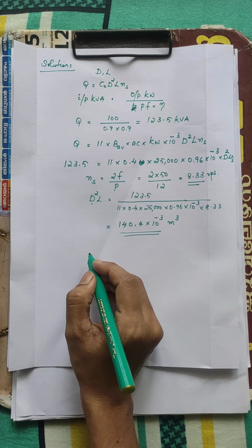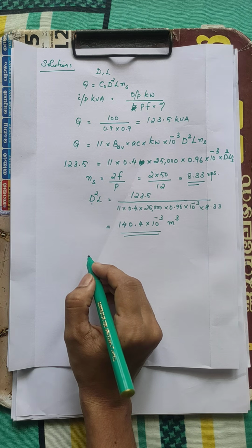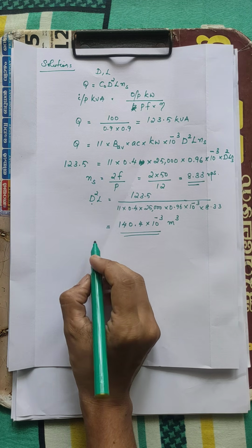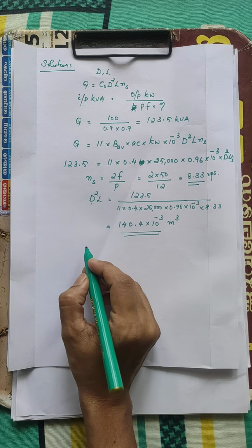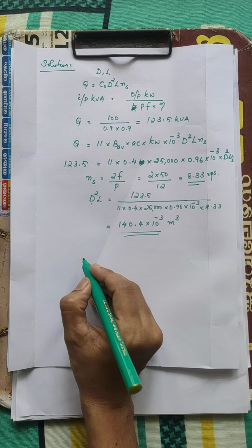For different design specifications, different values of L by tau ratios are there. But in this particular case, the design specification needed is the best power factor. In the question, it is given to choose main dimensions to give best power factor.